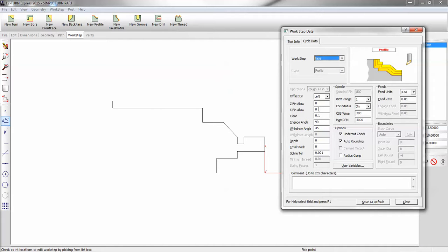If you want a finish allowance, now let's say I want a couple passes on the face, you can use this thing called total stock. We'll put 0.05 for stock, and our depth will go with 2.5. Or if I want to do passes, I could go 0.05 divided by 3 passes, and it updates for me.